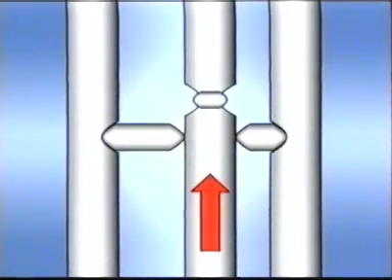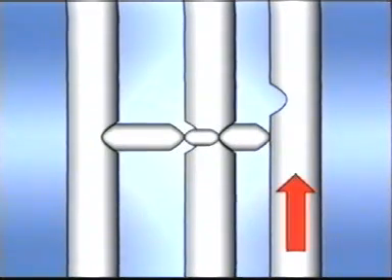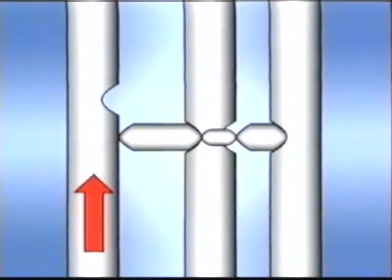When the central shaft moves up, the two interlock pins are pushed out and inserted into the slots on both sides to lock. Similarly, when the shaft on either side moves up, the pushed interlock pins lock the other two shafts in position. This is how the double meshing prevention mechanism works in W58.